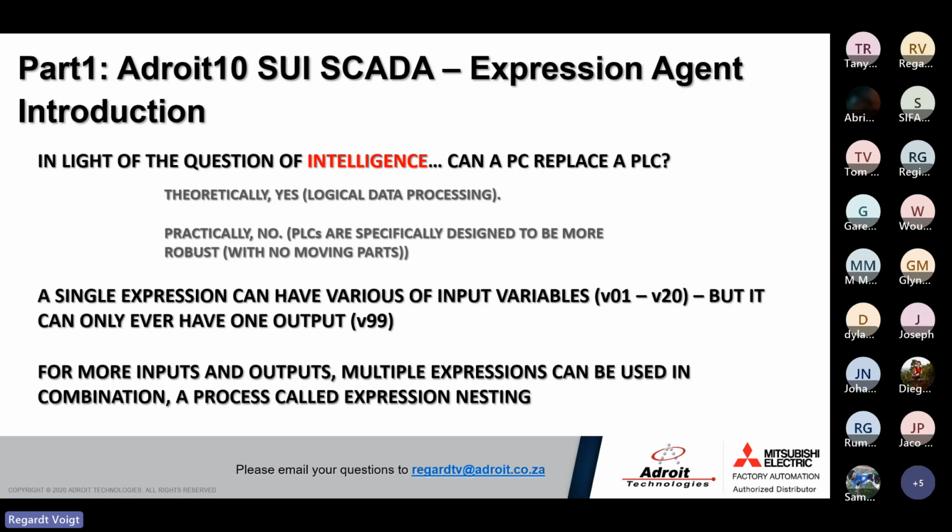You will, in most cases, need both these components in a process for decision making. Although I would just want to add that it's recommended that the PLC handles most of the calculations and logical operations, as that's its primary function, whereas an HMI or a SCADA has additional functions, and decision making is just a secondary function of those two tools.